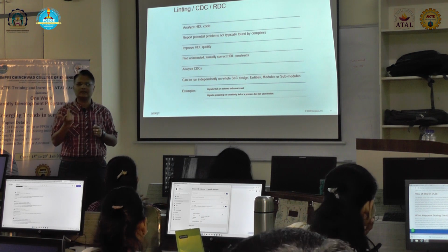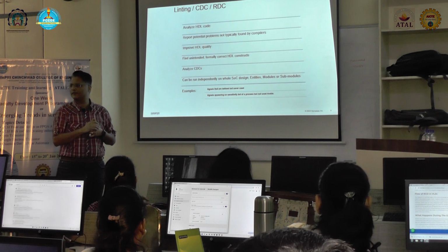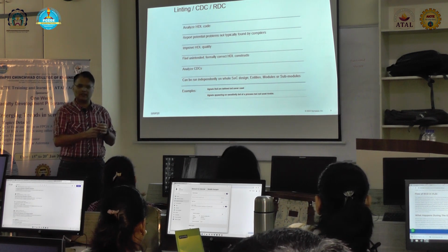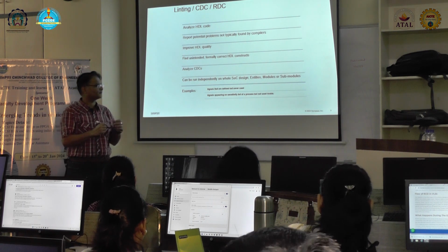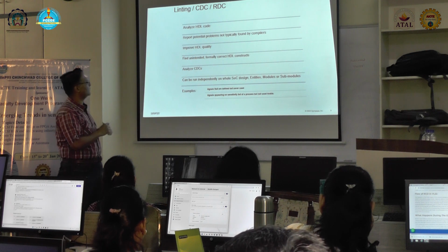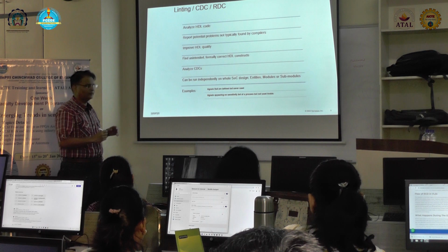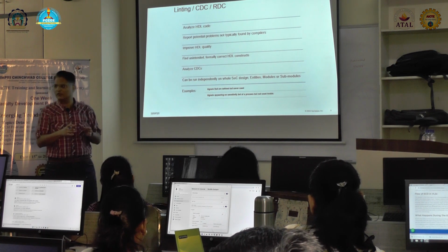So why are synchronizers necessary? Can anybody say? What happens if I don't use the synchronizers? Right, so basically there will be metastability. Using synchronizers, what we ensure is that we don't get into that problem.